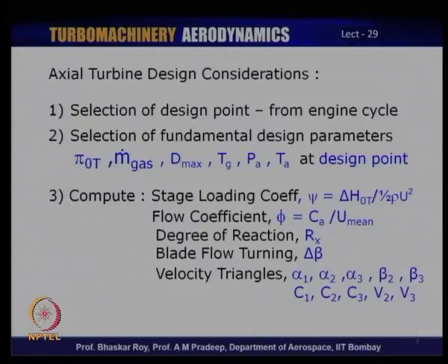So, depending on which stage of turbine you are embarking on, you need to decide the entry temperature to that particular stage of turbine. If you are starting off with a multi-stage turbine, the first stage entry temperature needs to be decided, which of course, is coming from the combustion chamber.